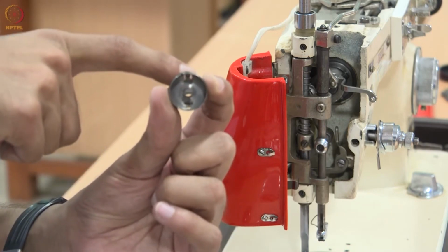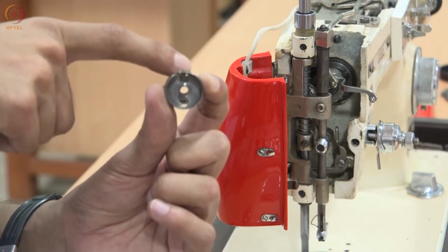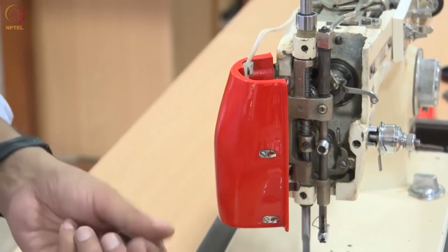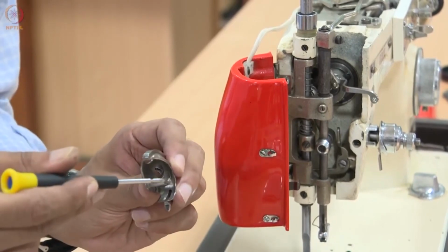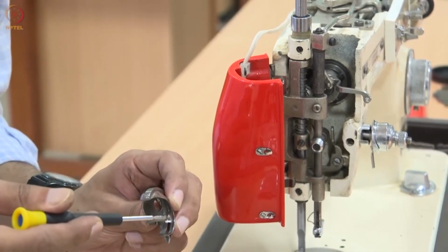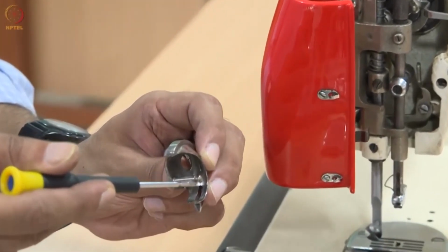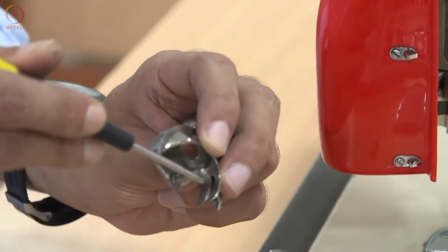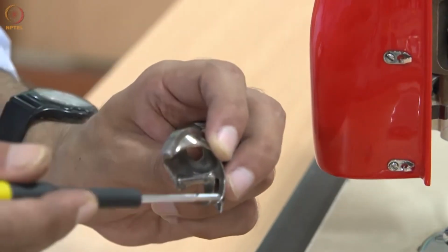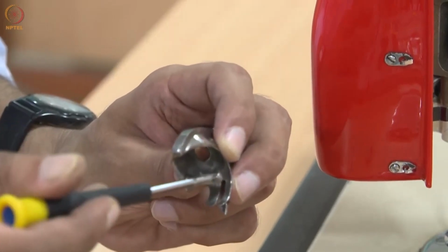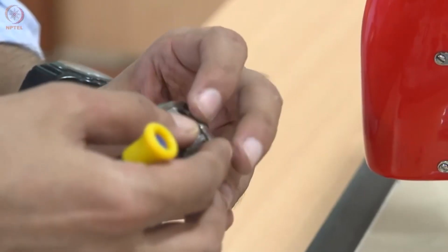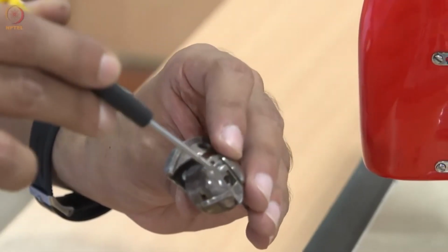You can see a slide that goes up and down. This slide basically engages a groove on this shaft, and the top part of the shaft is crowned. We call this crowning, so it's a smooth surface. So we have a shaft, there is a groove on the shaft, and the top part of this shaft is crowned. When we assemble this, please pay attention to the lever.